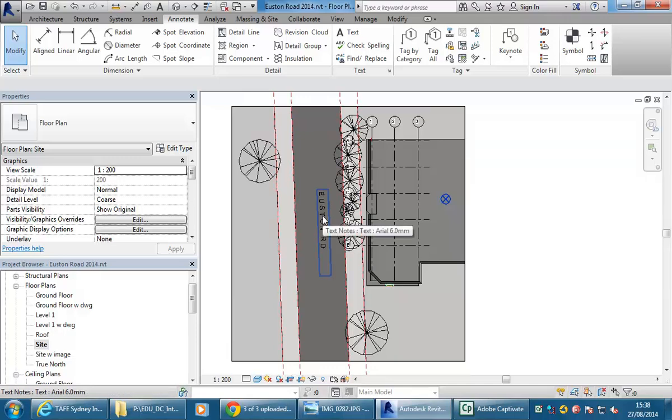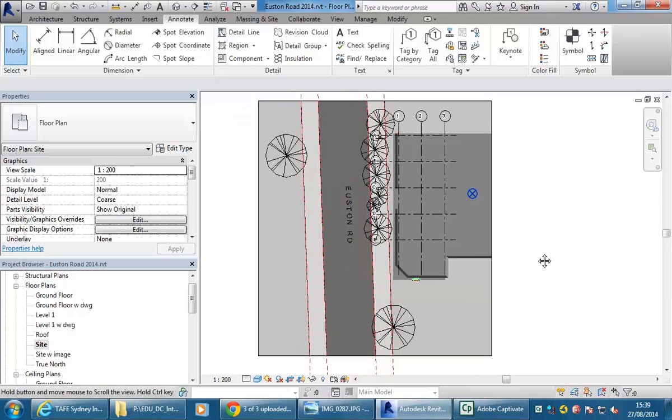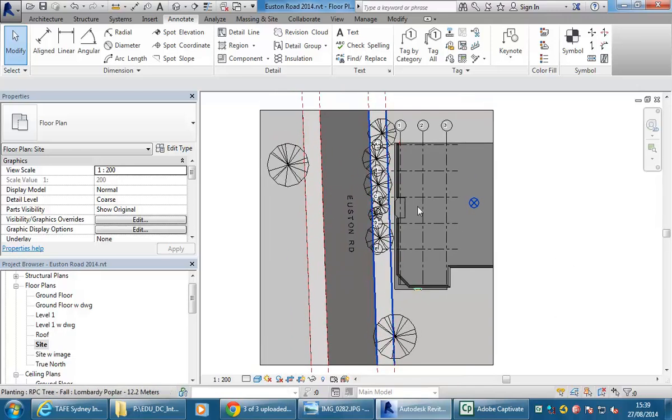So, and that's really the secret with things like site analysis plans. Put as much descriptive text as you can. So a lot of things, people often will try to draw them with a lot of detail for site analysis plans and make them into a really time-consuming thing, when really you can just describe a lot of those elements. So for example, the building itself would be a rectangle with a note. So just think about those things, and that really is all you need for your site plans.